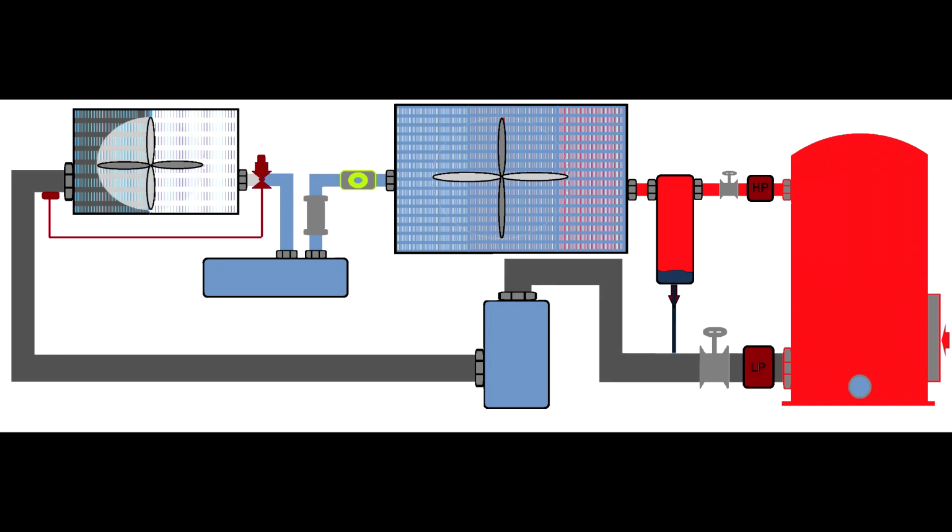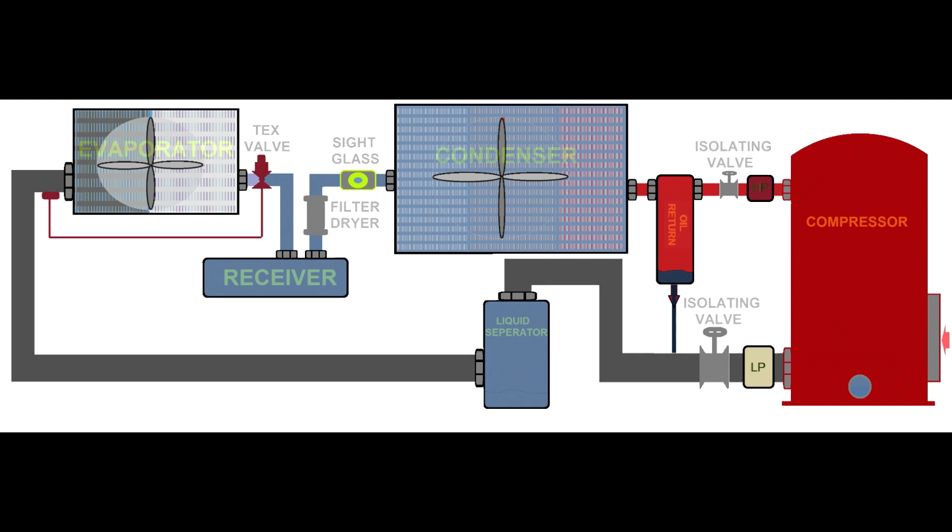The compressor gets very hot if you starve the system of refrigerant. Look, the evaporator is only half iced up, and the suction line is warm, so not enough refrigerant is coming into the compressor, and the compressor gets red hot. Soon the compressor will die.